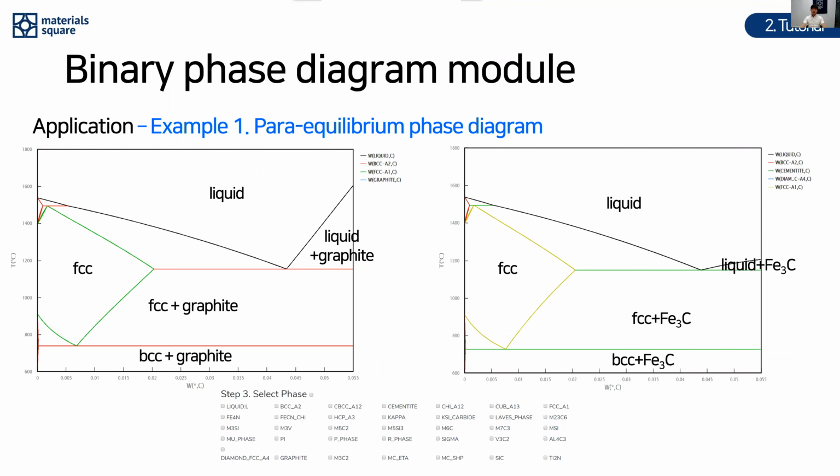In this section, I want to explain metastable equilibrium. The following left figure is for equilibrium iron carbon binary phase diagram. However, in practice, when manufacturing carbon steel, in the microstructure, not graphite, but Fe3C cementite exists. Energetically, graphite is more stable than cementite. However, in aspects of thermodynamic kinetics and reaction, practically, it is impossible for graphite to appear in the microstructure.